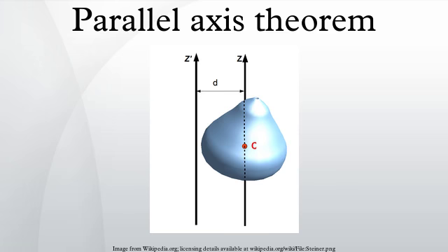Where d is the vector from the reference point S to the center of mass R. Identities for a skew-symmetric matrix. In order to compare formulations of the parallel axis theorem using skew-symmetric matrices and the tensor formulation, the following identities are useful. Let [R] be the skew-symmetric matrix associated with the position vector R = (x, y, z), then the product in the inertia matrix becomes the following.